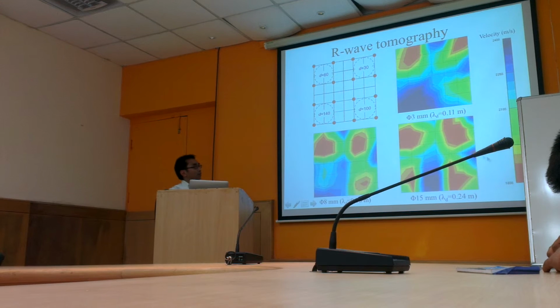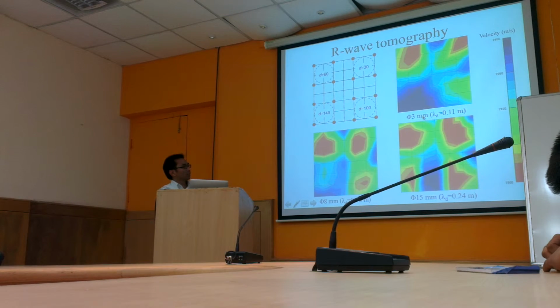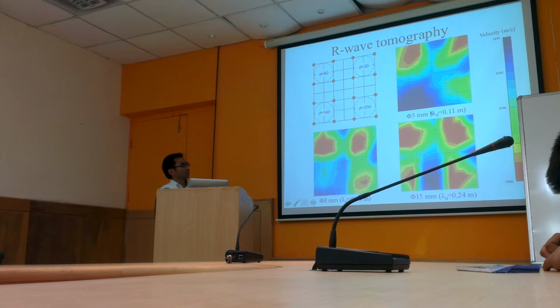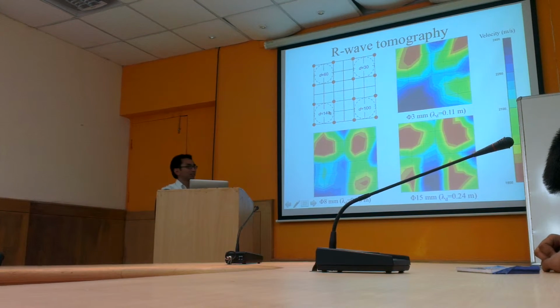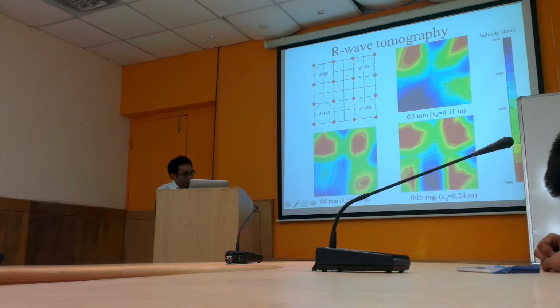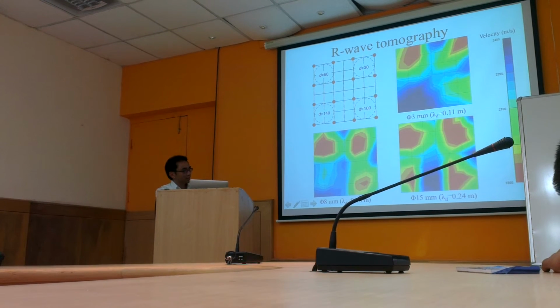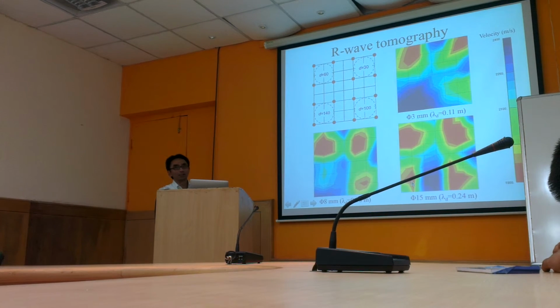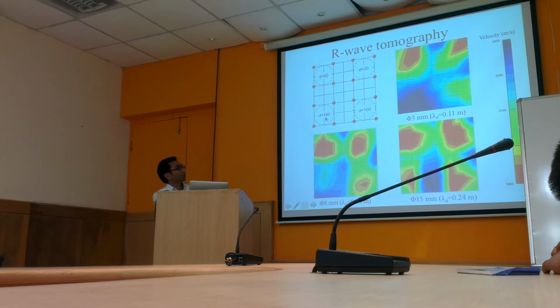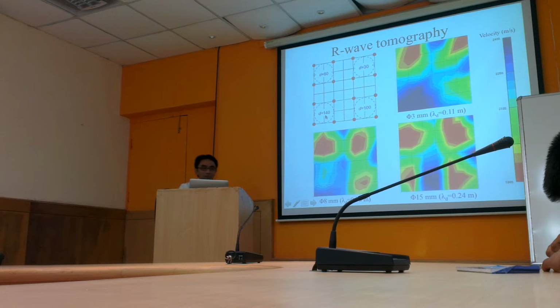So you see, when the penetration depth of the wavelength is small, probably you might not be able to capture the presence of a crack which is deeper than that. But after that, if you change it to a bigger size, the results are very promising. It shows that basically we can use it to visualize all the cracks, up to 140 millimeter.